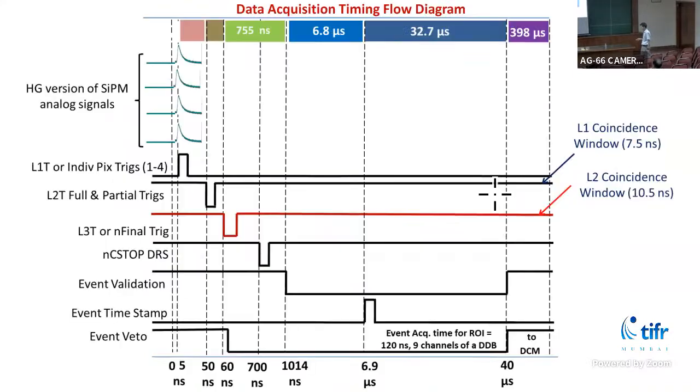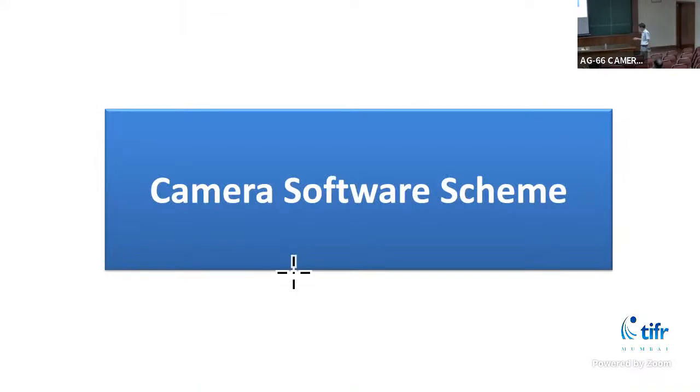How are your signals going to remain waiting for the DRS to digitize? In this figure, the way it's shown, your digitization would start after about 7 microseconds. Your analog signals should be sitting somewhere, right? Yes, analog signals are sitting. In the next slide, I'll show that.